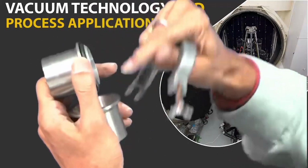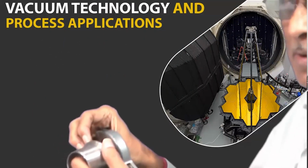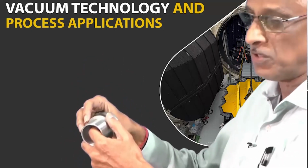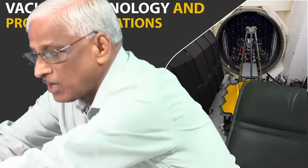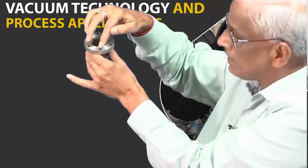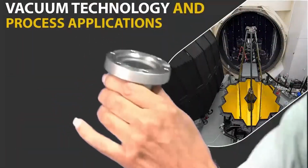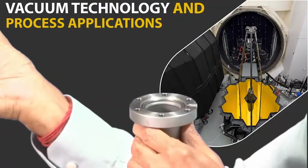These are called O-rings because it looks like an O, and these are neoprene in normal vacuum, Viton for high vacuum. But none of these things are good for ultra high vacuum. In ultra high vacuum, you require a flange like this, conflat flange, wherein I will put a copper gasket and another conflat flange like this.